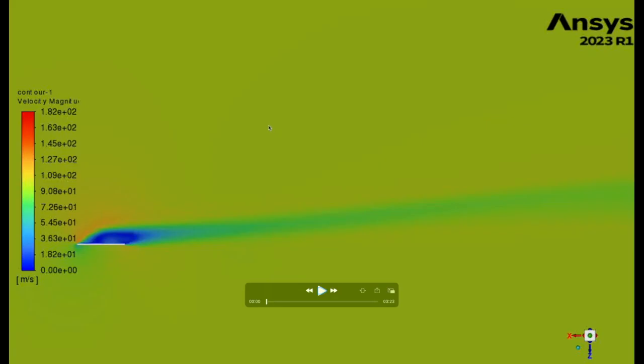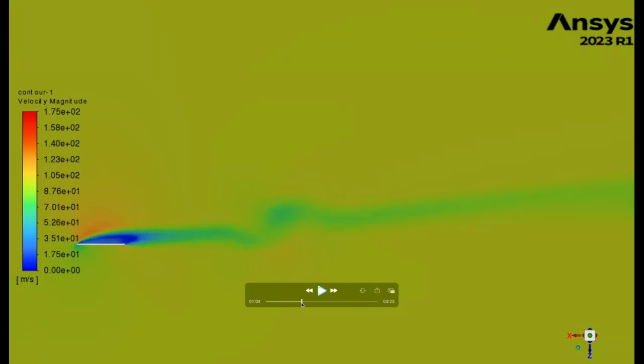A few interesting results I got. This is the animation from one of the transient simulations I ran. This is with time step 1e-5 and velocity of 100 meters per second and angle of attack of 10 degrees. And it's the same mesh I just described. I'll just scrub through it because the video is actually very long because the time step's so small, and this movie player doesn't know how that works. But you can see it sheds a vortex, and then the flow stabilizes.